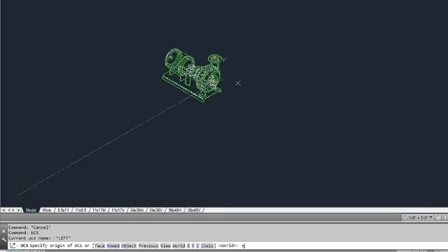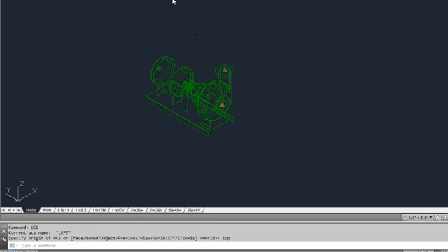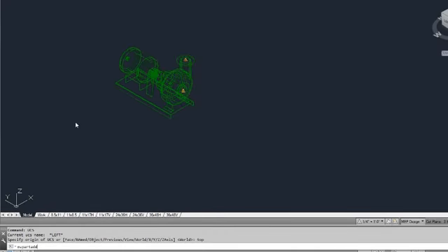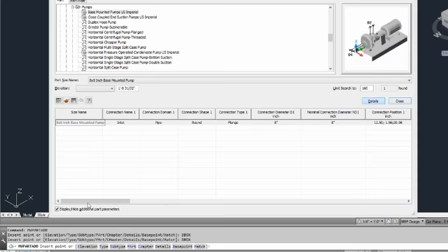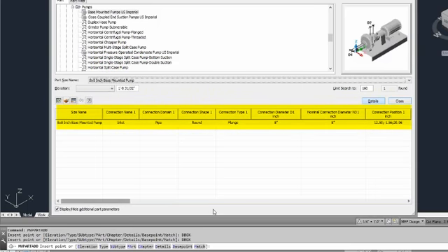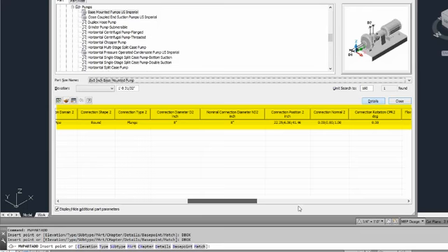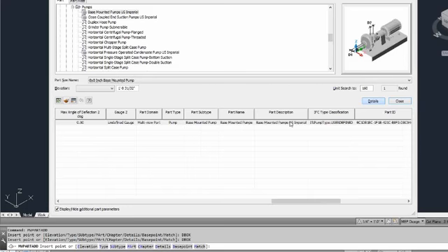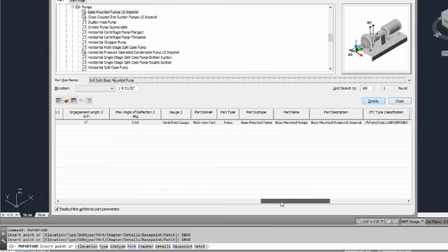So if I look at this pump, when I added it through the command line through MVPart add, and I'll go back there real quick, you can see all of these different parameters on it. That's what I meant by having some intelligence to the part. It has a part name. It has a part description. If you're using IFC in any way, this has an IFC classification to it. All of this stuff is available using property sets if you need to schedule that sort of information.